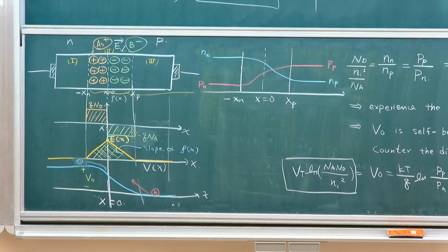Those are for power applications. It requires sustaining voltage up to 1,000 volts. So think about how you build the tent, the triangle. How do you spread the potential out in order not to have a very high electric field to sustain this voltage? It is a very important thing in device engineering, especially in power device designs.